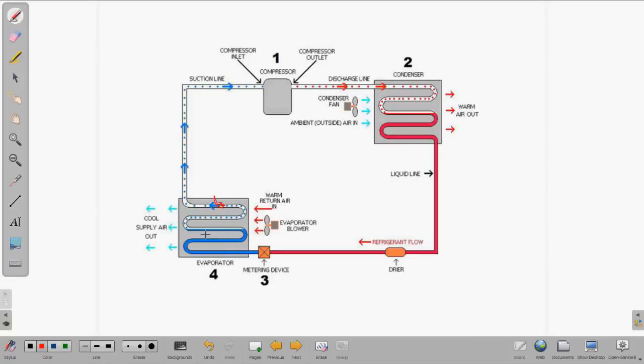And so effectively, you have cut cooling down, in this instance, by half. Now what's happening, instead of changing state throughout this coil, it has stopped changing state right here and is starting to pick up superheat long before it's supposed to in the evaporator coil. So it's now picking up superheat from the air and coming back to the compressor with a ton of superheat.